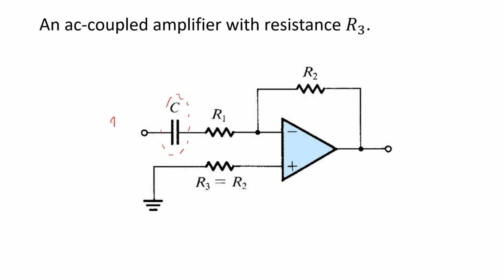We may introduce this AC coupling for any number of reasons. For example, we may have introduced it to mitigate the impact of DC offset voltage, as we discussed previously. So in this case, note that the input bias current IB1, being a DC current, must flow entirely through the resistor R2. That therefore gives rise to a voltage drop at DC across R2 of IB1 times R2.